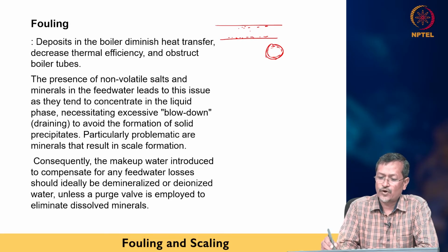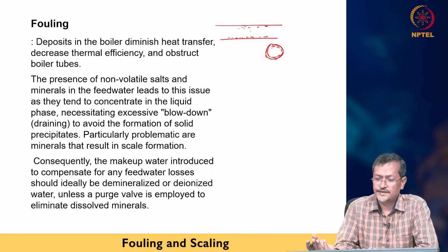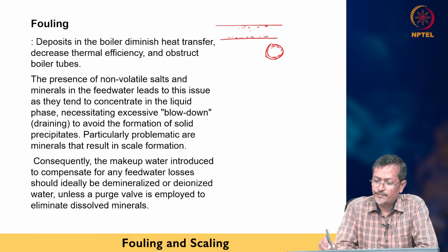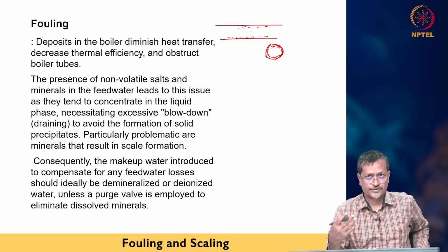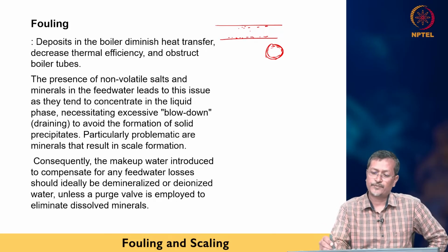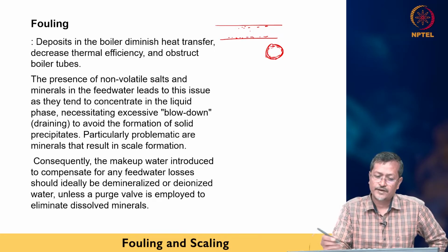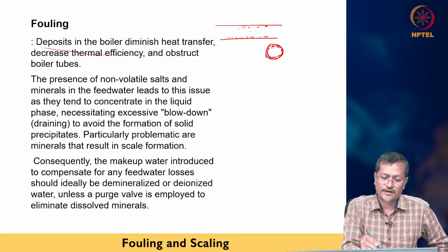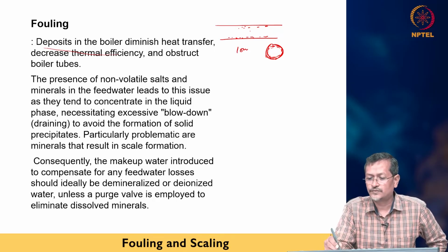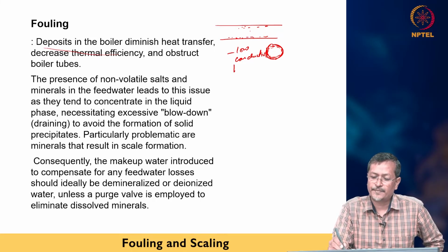When it is blocked, your fluid flow can be stopped. Another thing is that the pipe or tube metal will have high heat conductivity. Now you have deposition, and the deposited material will have low thermal conductivity. Again, it will be blocking the path.